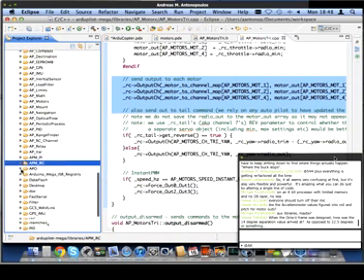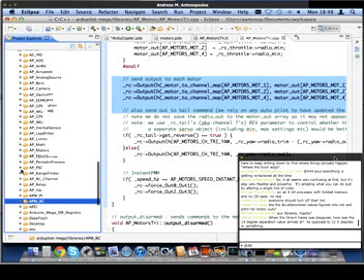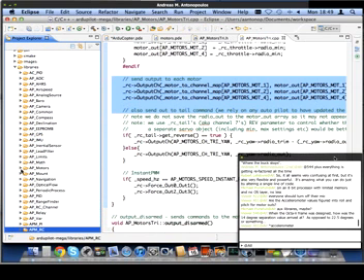So that is kind of it. Just as a recap, we saw how we decode the switch, how that is translated into control modes for the yaw, roll, pitch, and throttle, how those are fed into the PID loops inside of the attitude.pde, and finally how those are fed down into the motors. So let me break for any questions.